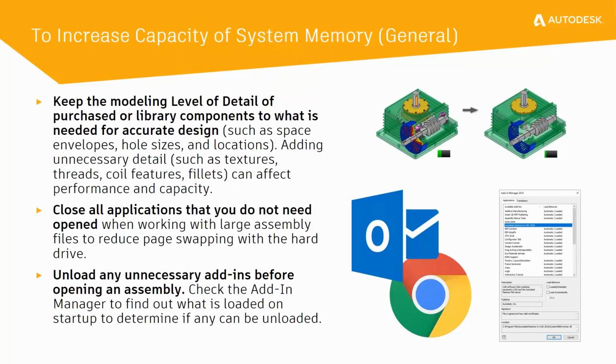news. And the other thing you can do, and we mentioned this in the part 1 of the webinar, is to unload any unnecessary add-ins before opening an assembly. So inside of Inventor, you've got your add-in manager. Look to those areas of your system that you don't use commonly to unload them or stop them from automatically loading when Inventor loads as well.